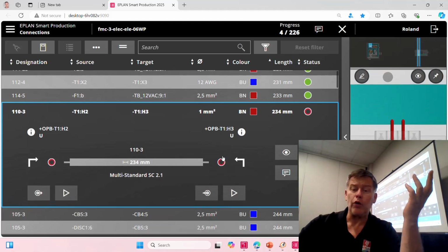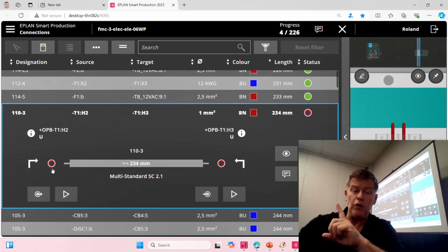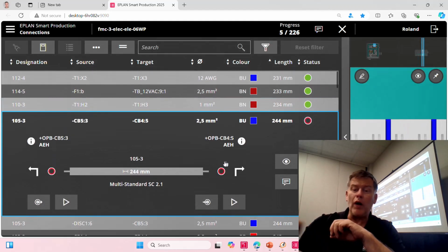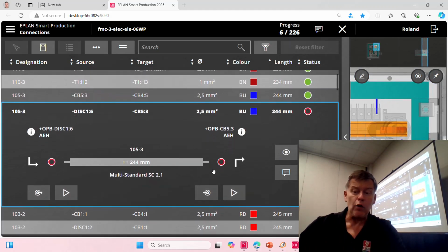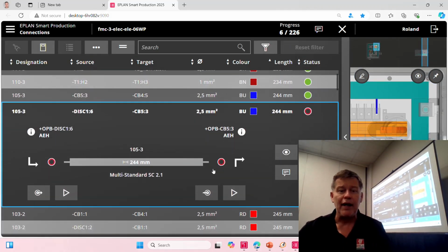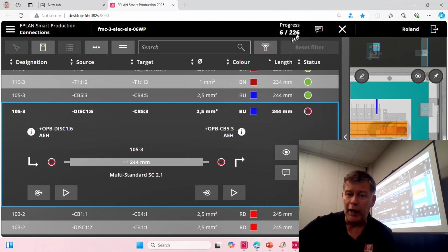It's kind of a no-brainer also because anyone can help. We can be 2 people, 3 people at the same time, clicking in here and taking one wire and installing it. And this wire installing that we have here, or also called wire landing, will take roughly a minute to a minute and a half, maximum 2 minutes. So this means after your initial assembly, you can count the number of wires we have up here, 226, and I can pretty much say that anywhere between 226 and 300 minutes, this complete project will be handled.